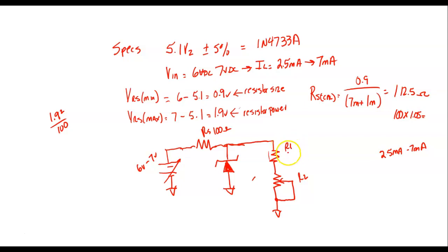And another thing nice about a 100 ohm resistor is when we set these currents, this is a 10K pot, instead of trying to measure the current, I can measure the voltage drop across this resistor. And I can use it as a shunt, and I can calculate resistance. I can calculate current. So let's go ahead and do that.